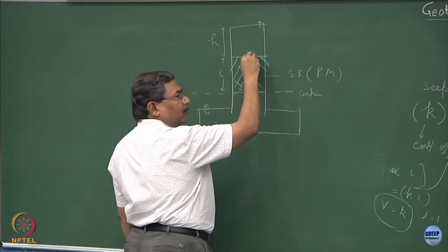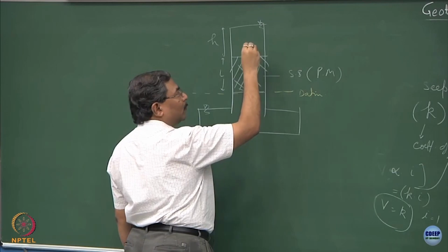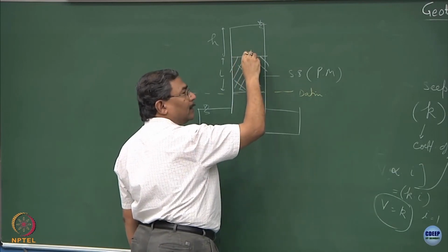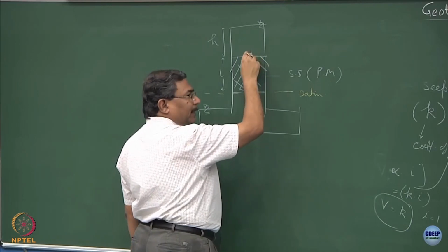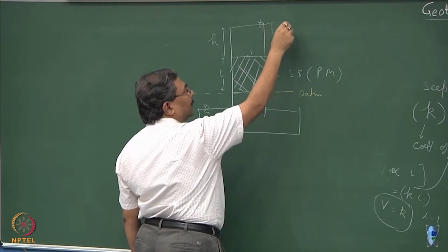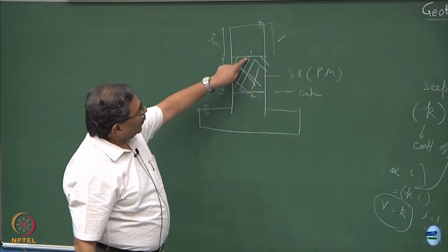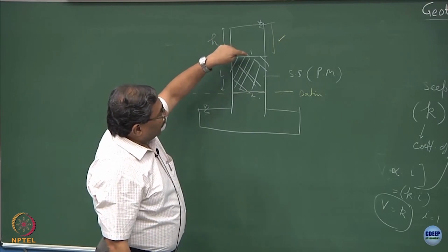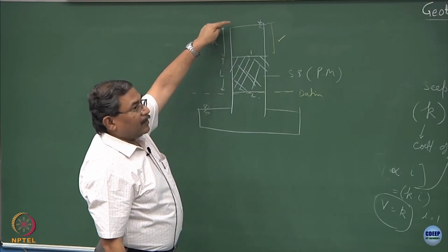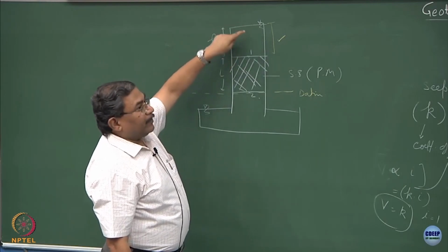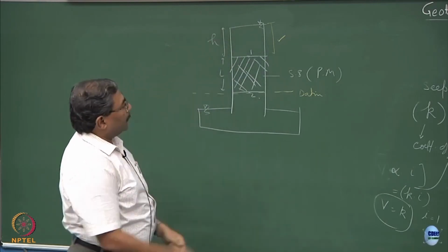Elevation head at point 1 is known. What you want is pressure head. How would you obtain the hydrostatic pressure head over it? If you put the piezometer here, this will go up to this height, clear? So, that means the piezometric head at point 1 is H, rising up to the height H to equilibrate with the atmospheric conditions.